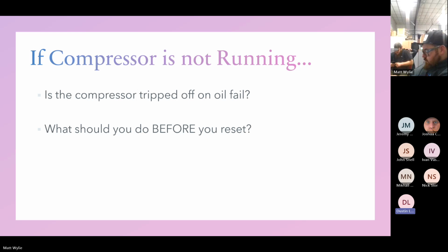And it's a hard one to catch. Those are the ones where the guy goes and resets it and it runs fine while they're there. But then guess what? That system goes into defrost. It's nice and hot, it comes out of defrost, and the expansion valve opens wide up to cool it back down. It's already running low superheat, but now you're sending so much liquid back to the compressor, you're pushing the oil out. So that's a really common one.